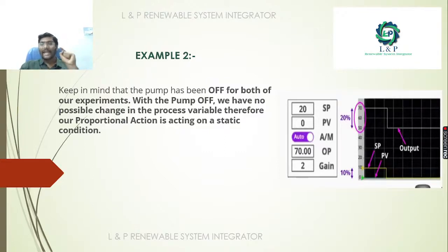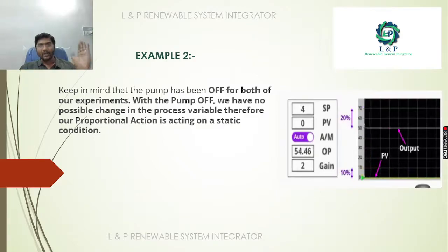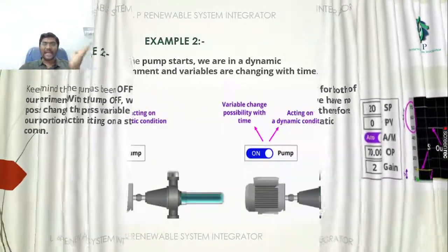Now, in the present value, you can give any sort of value. For example, based on the temperature, you need to control the damper actuators, or based on the pressure or flow value, you need to control the speed of the pump. Like this, based on the flow value or a present value, you need to control the valves which we are operating in the pipelines. Whatever you want, you can provide that concerned output in the ranges, along with the set point ranges. Now let us try to move on with another example.